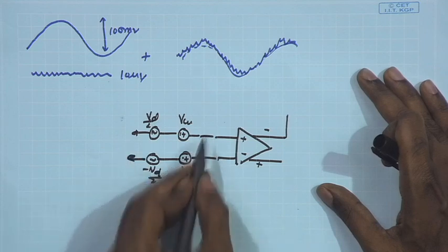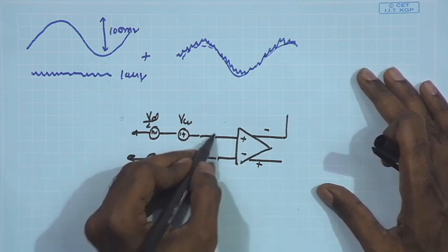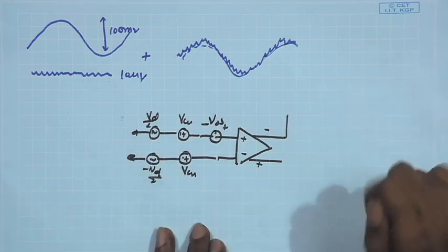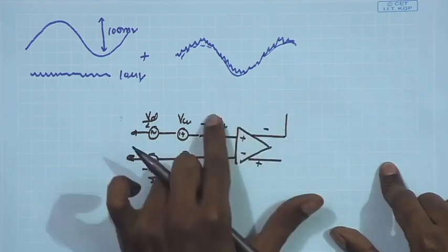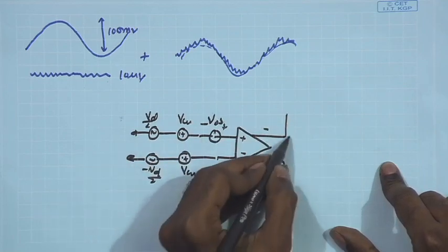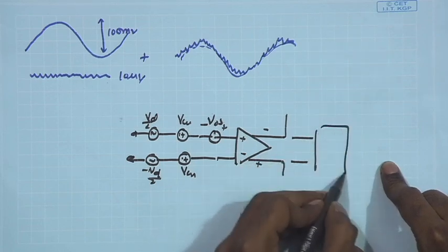These two are applied to the positive and negative terminals, and then one of them is having offset. So suppose you are having a V offset. If you do not have the feedback from output to the input, you have controlled the output DC point using common mode feedback. So this is controlled using the CMFB circuit.